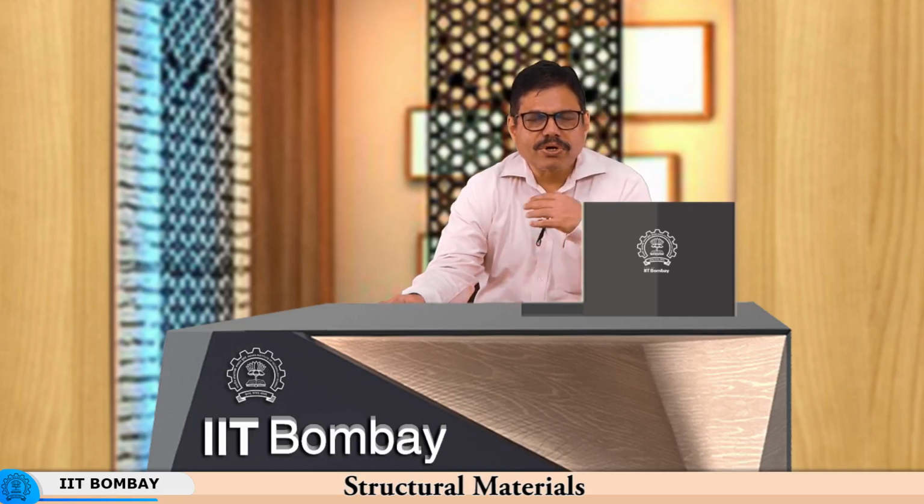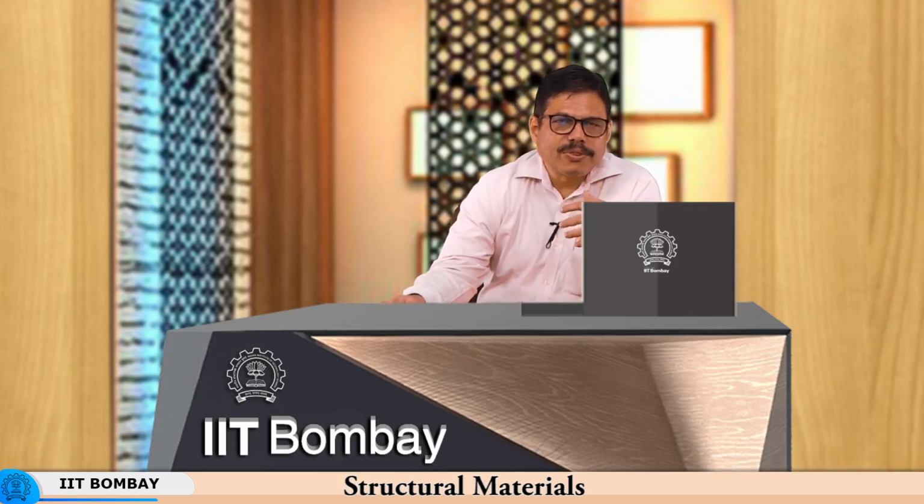And what is the composition of the last solid remaining prior to the complete melting? So you see that this is the chemical composition, and if you are going to slowly heat the material, it means that you are looking at equilibrium heating. Just as we were talking about equilibrium cooling, the heating rate here is so small that the two phases are capable of being in equilibrium as long as the temperature is maintained. So that is what it means.